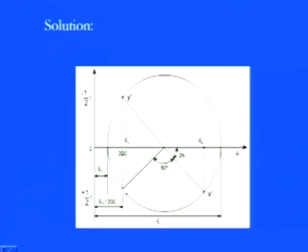So, you see here this new coordinate will give you the new values in the x as well as the y direction, and then we can say that this is my epsilon theta, which is the direct strain component at an oblique plane, and as well as you can get the gamma theta just by taking that part on the vertical direction. So, this vertical direction will give you the strain component in the y direction. This projection on the x axis will give you the strain in the x axis. So, you have both the components, the normal strain component and the shear strain component, by just dropping those projections from the x as well as the y direction.